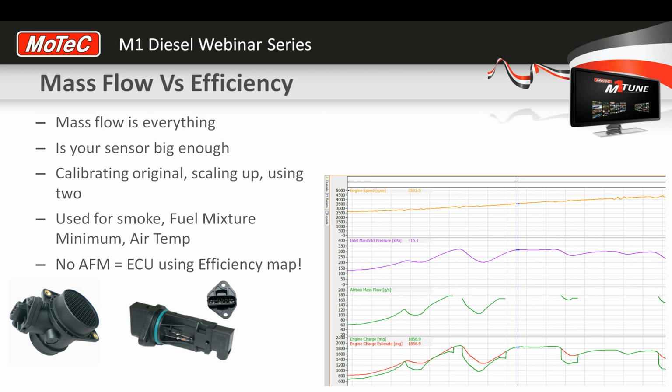If you're not using those tables, then as you've probably seen in the previous webinar, the whole fuel system and the fuel model just works on pedal position multiplied by the fuel mass limit table. Whatever's in the fuel mass limit table at the particular operating point is multiplied by the percentage of where the pedal is.